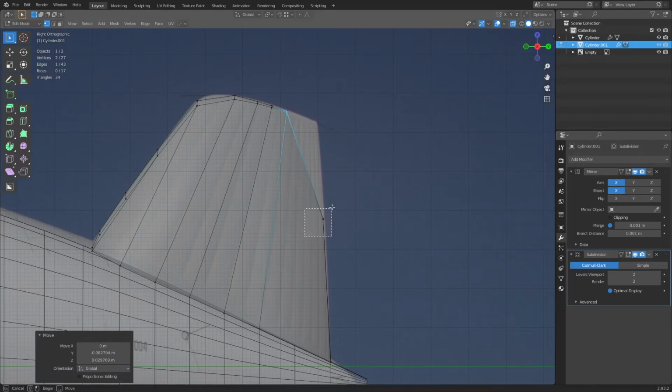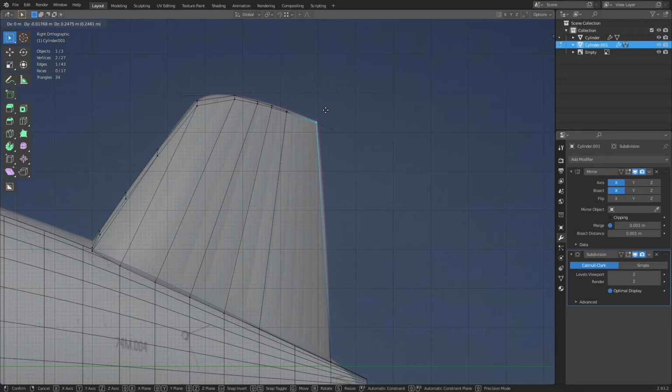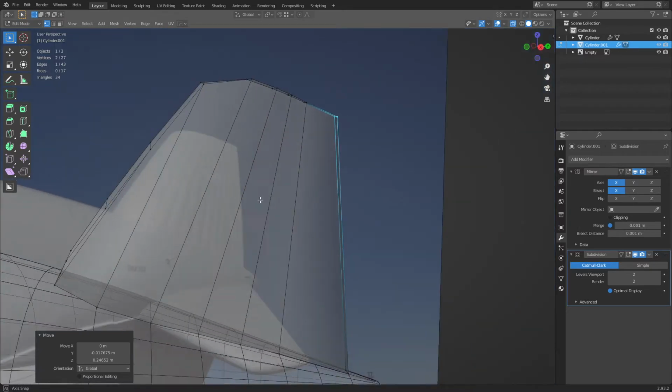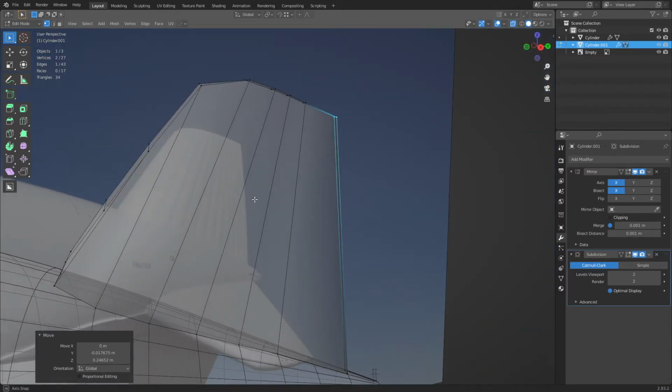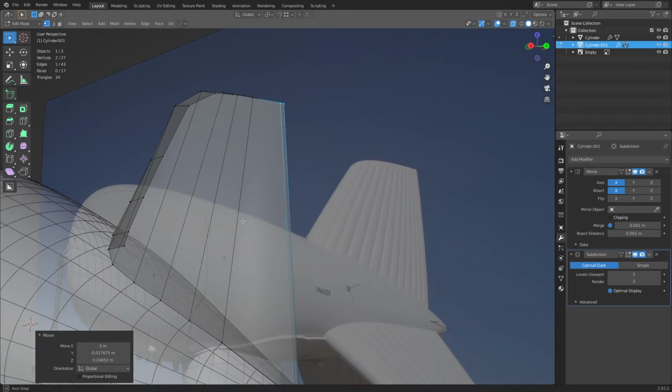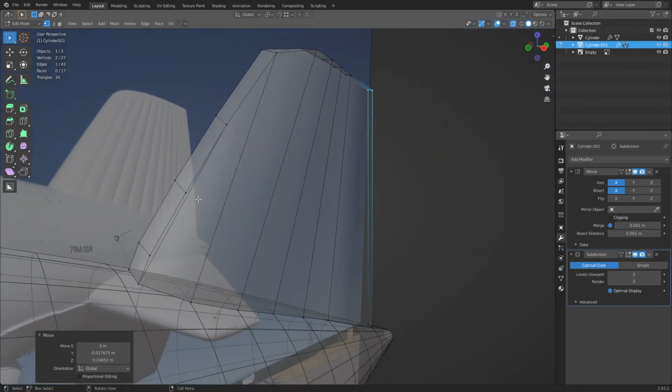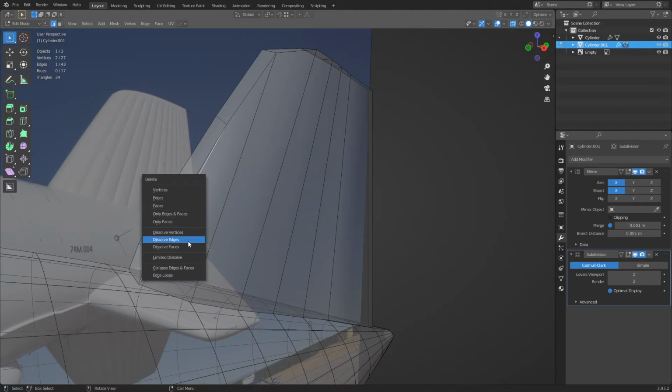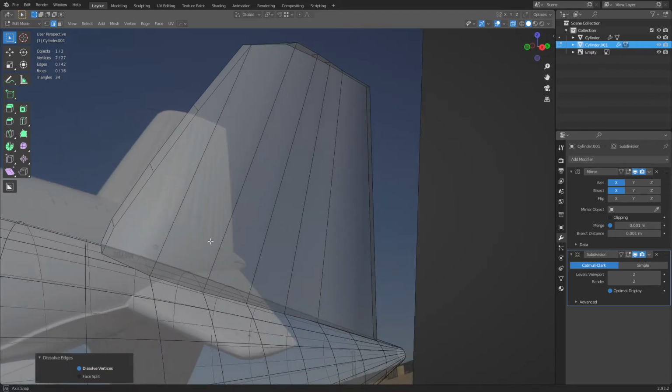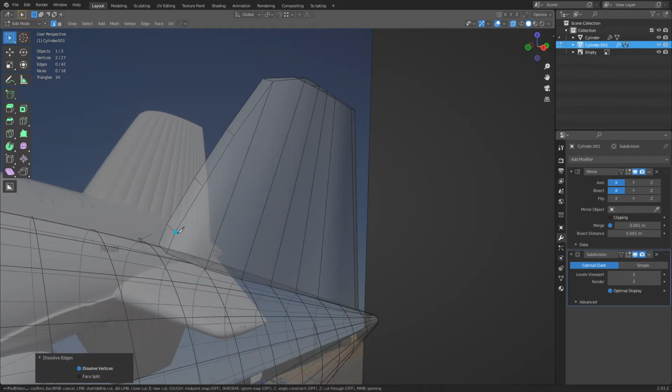Now, one additional vertex will let us get all those back ones in the same direction. All right. So solve that one. So I'm just going to do a cut all the way through to here. Pressing the E. So knife tool with K and then do this and hit E. We'll turn it into all quads here.